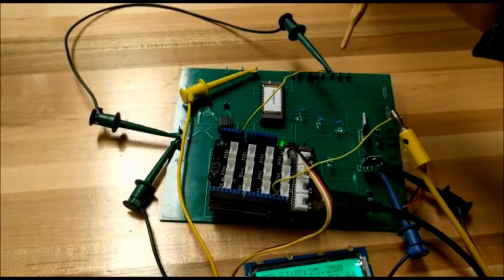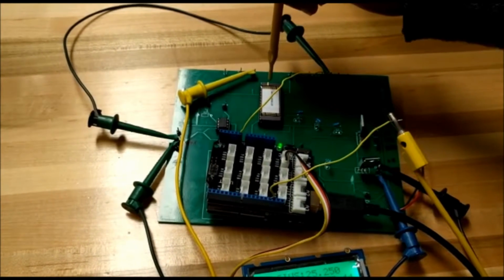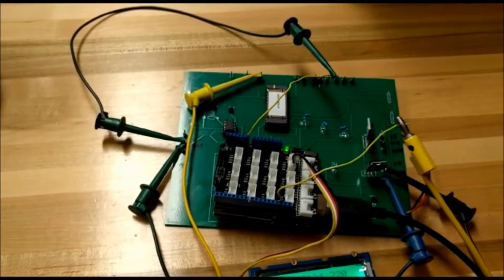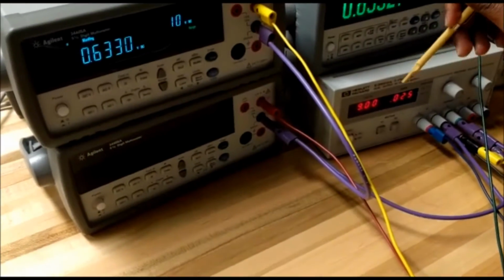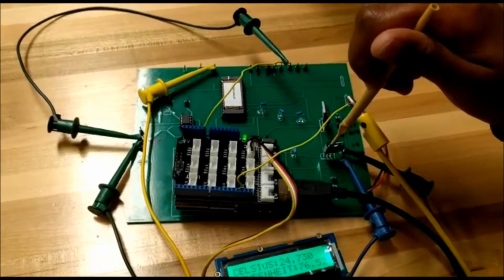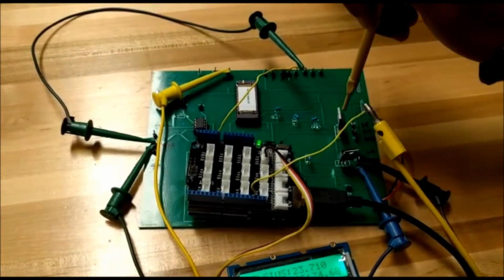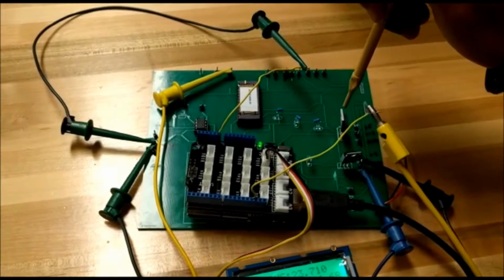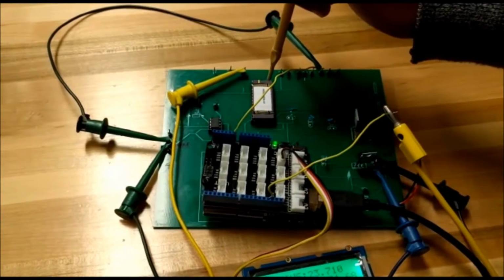Now demonstrating our temperature sensor. This is our chip. The chip is powered using a 9 volt power supply over here, which is first passed through a voltage regulator which converts it into 5 volts, and then we use another voltage regulator to convert it into 1.2 volts, which is required for our chip to operate.